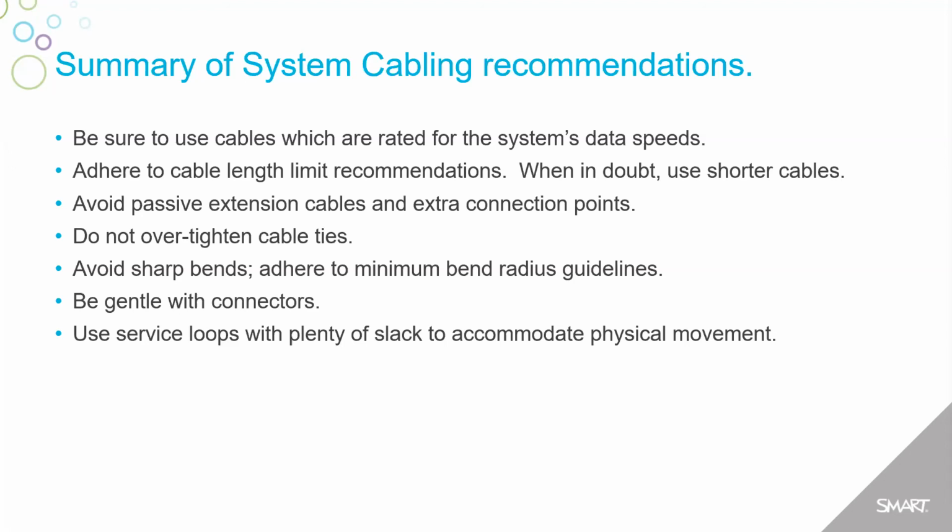Do not over tighten cable ties. Help your cables last longer. Avoid sharp bends. Pay attention to the minimum bend radius guidelines. Be gentle with connectors, and use service loops with plenty of slack to accommodate physical movement when needed.